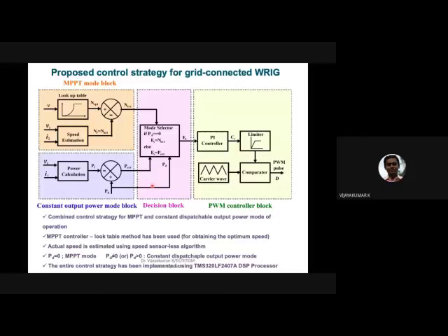In this case, we have given stator voltage and rotor current as feedback. You have to give stator voltage and rotor current as feedback. That algorithm I have given in the future slides. If you are really interested to work on speed estimation techniques, we can have a look at the paper.